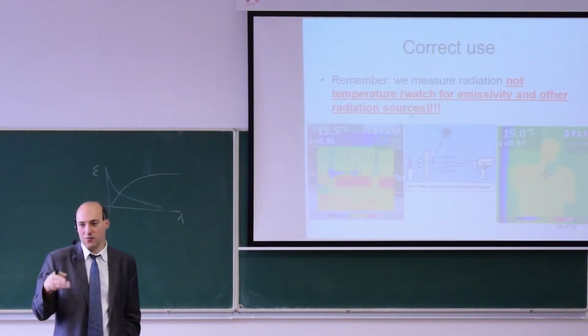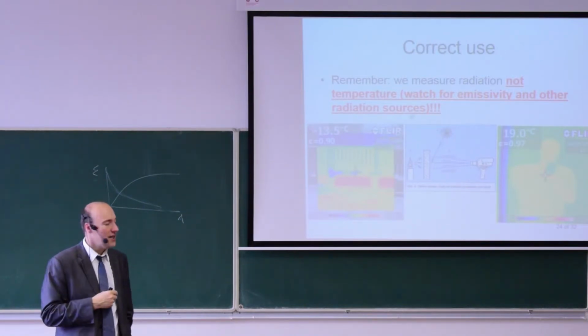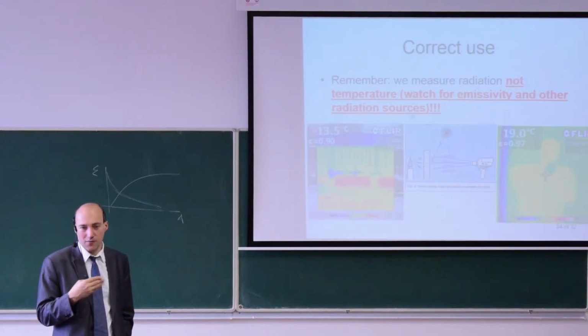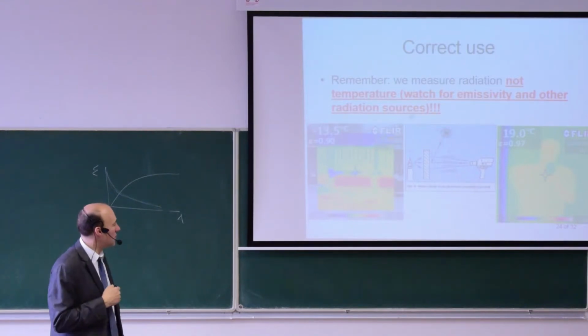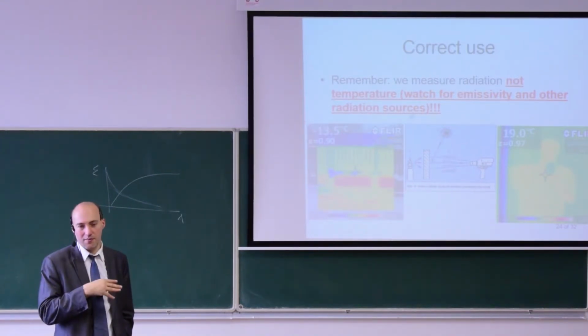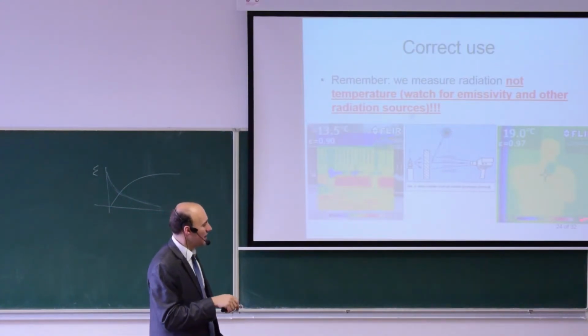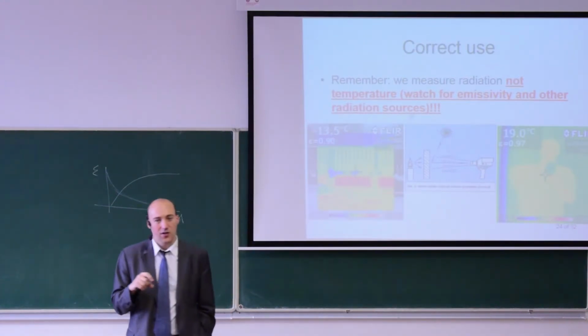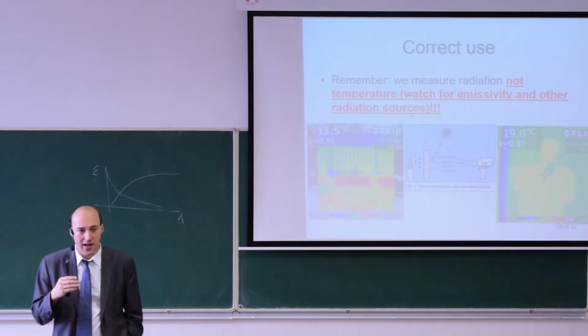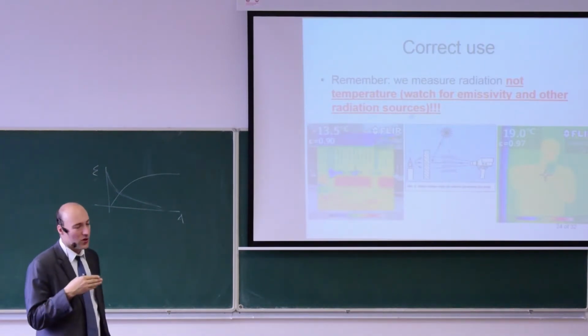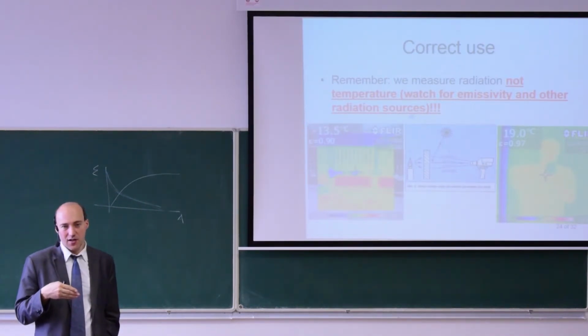It's the same as if you play with a metallic sheet, you will get reflections of all the surroundings, but not from the material itself. So what you can do here is apply stickers, or paint the surface, if you want to get the emissivity correctly.